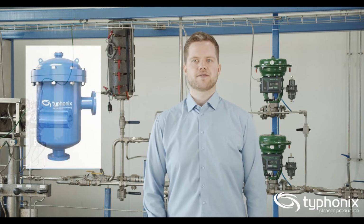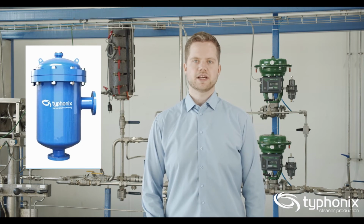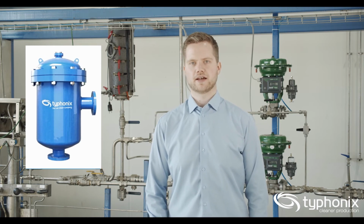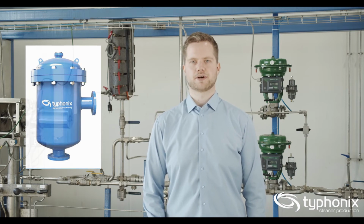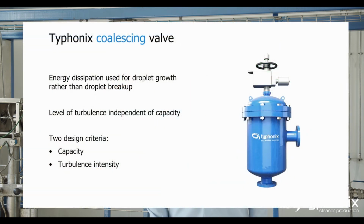The coalescing valve technology is in some sense more different to standard equipment than the coalescing pump. But the core principle of the valve is still a plug cage valve, so it is similar to standard equipment. But the energy dissipating part of the valve, where the pressure drop happens, has been optimized to promote a turbulence intensity that is most efficient for droplet-droplet coalescence.